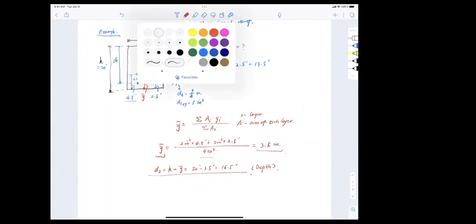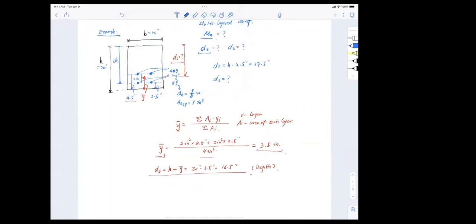Right. What about moment? And to do that, I need to know the properties of the material. So f'c, let's just say normal weight concrete 4 ksi, and I would say a Grade 60, and again, this means the yield strength of the bar is 60 ksi. Don't forget. Okay, and I need to find Mn, and while I'm at it, I also need to find my strength reduction factor phi here.